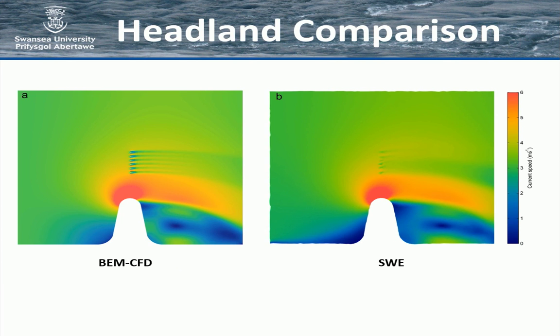And so knowing how to set the rotor rotational speed to give you something that's running at optimum, it's actually quite tricky. And so a lot of the work we've done recently has been to try and take away that complexity. So what we can do now, we can just say we want to run at TSR4, and the rotors now self-control to the right speed, which is nice. That takes some of the guesswork out.